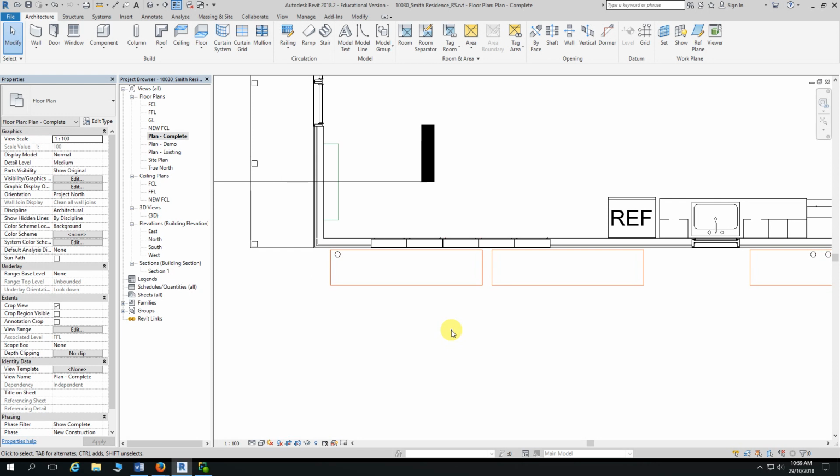No, I'm thinking of families that are part of the project that can't be loaded, and families that can be loaded. Okay, so you got walls, floors, ceilings, annotation, which are known as system families. Component families are loadable, so they're loadable or component.